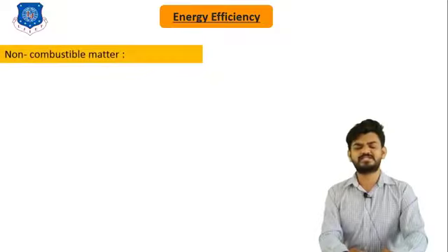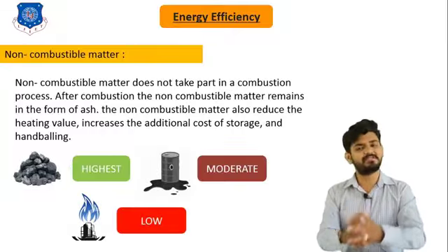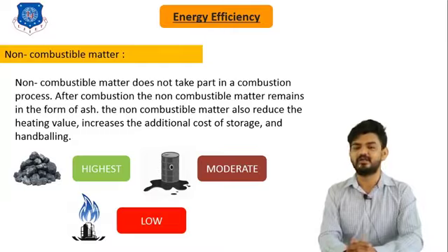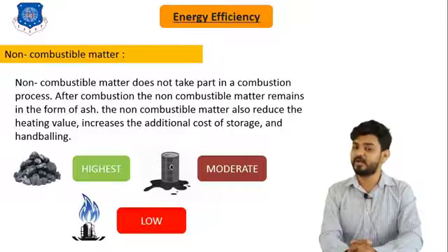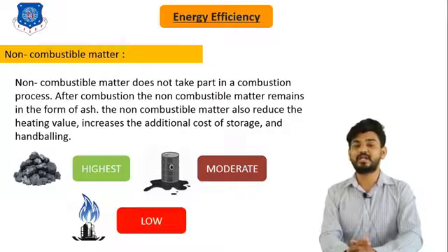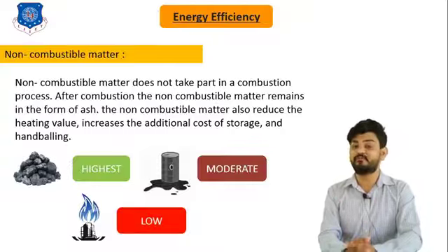Now let's understand the next property, and that is non-combustible matter of fuel. The non-combustible matter does not take part in the combustion reaction. After combustion, the non-combustible matter remains in the form of ash. It also reduces the heating value of fuel, and it increases the additional cost of storage and handling.